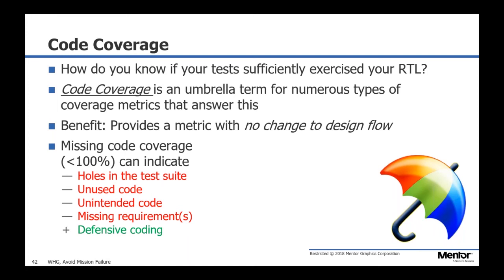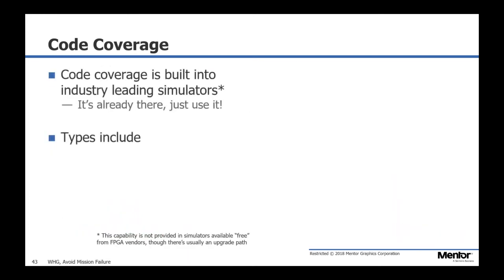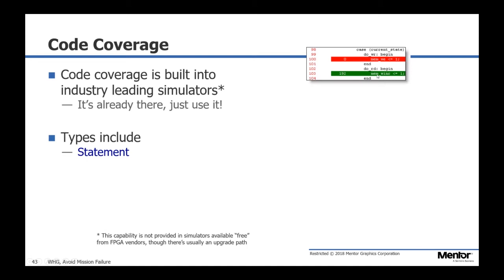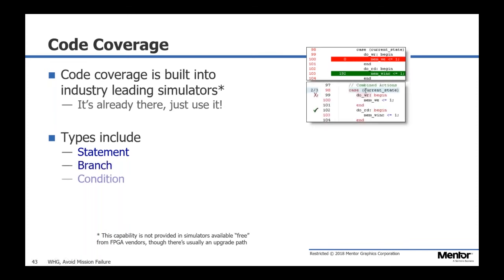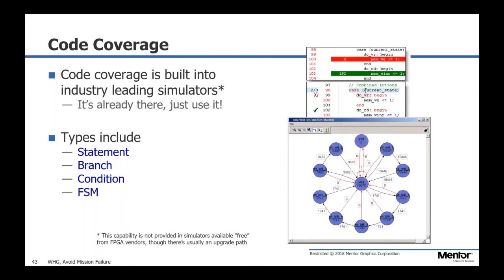Well, now the question is, do I have to write more tests to get that coverage? Can I actually get that coverage? Is this line of code coverable? Will I ever have a case where this is true? So there's all kinds of ways. Okay, this is going a little deeper. Like I said, conditional coverage, finite state machine coverage.